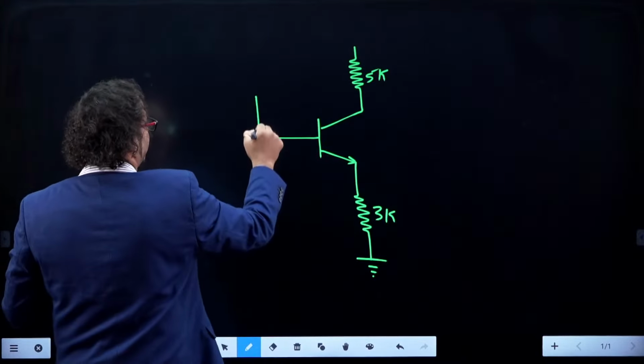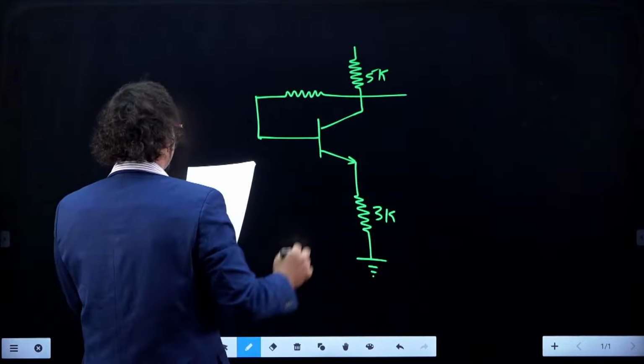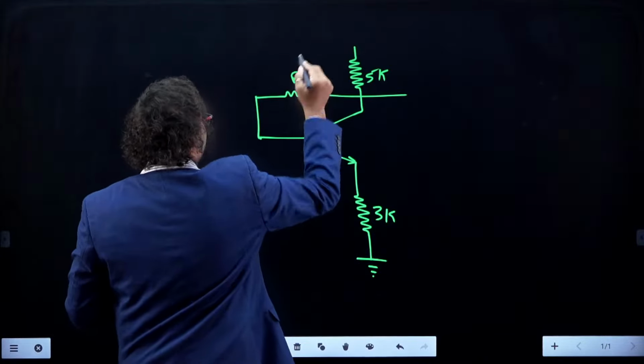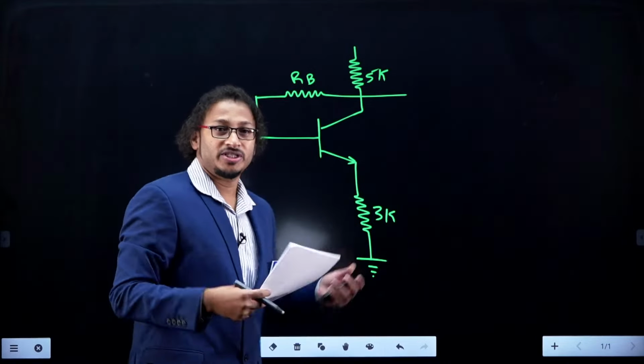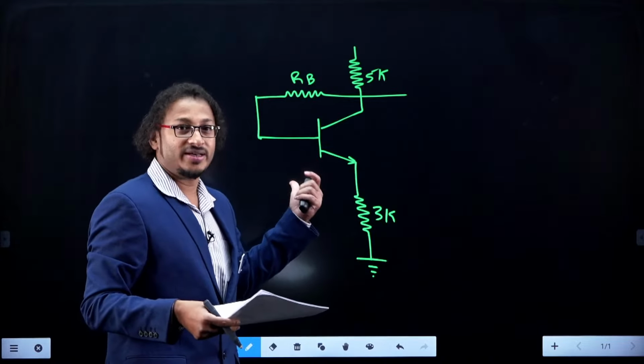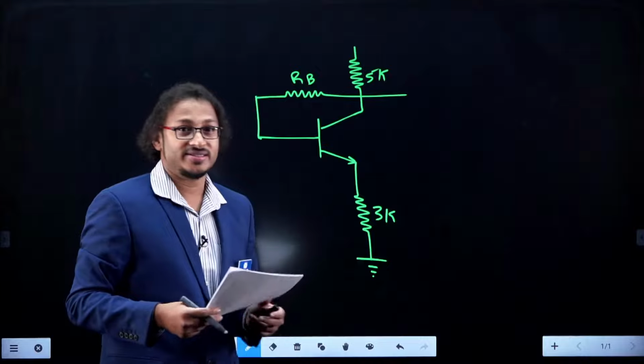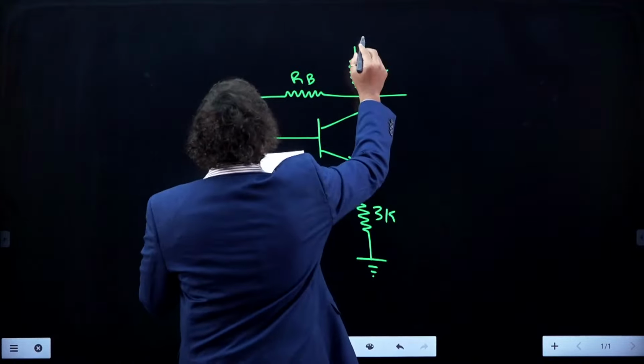Of course, it is completely a DC circuit, so no need of disturbing the sources we have here. If it is an AC circuit, as we discussed a lot, this must be a negative feedback with shunt mixing, and like shunt mixing, the input must be current and the output is shunt sampling, so the output must be voltage. It must behave like a transresistance amplifier. Am I right here? Anyways, this is given as what here?